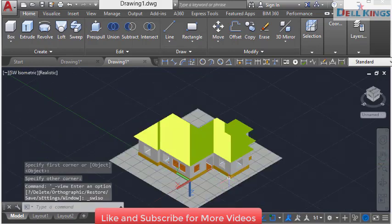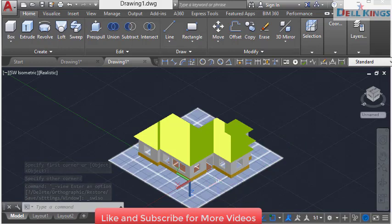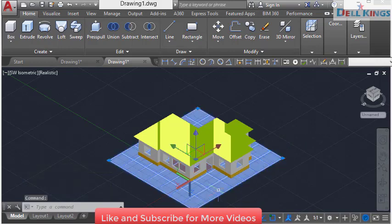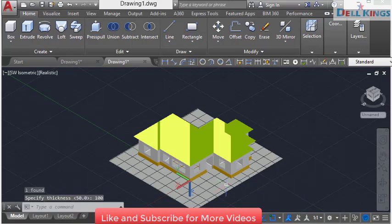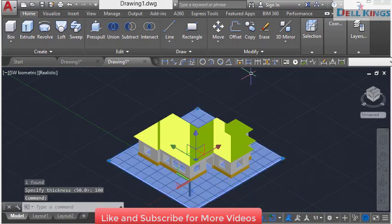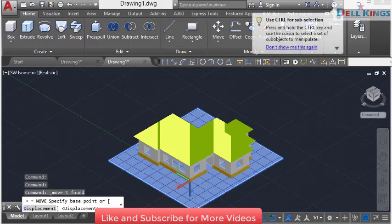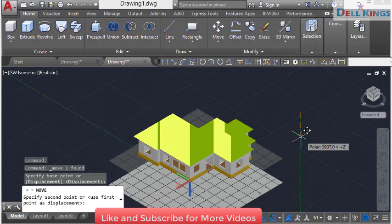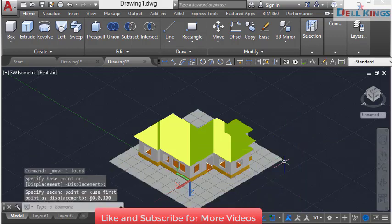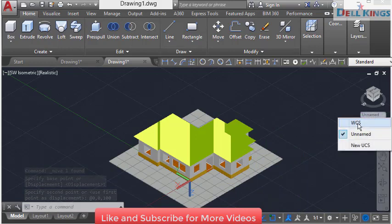So you're going to have this. So this is just a surface. We are going to change it to a solid. So select this and type TH for thicken and select the thickness to be 100. Type 100 and press enter. So we now have this, and we can now move this down. So select move, and so we have our UCS facing this direction with a Z pointing down. So we're going to move this by 0, 0, 100 and then press enter. So we have this looking like this, and we can now change our view from that to world view.